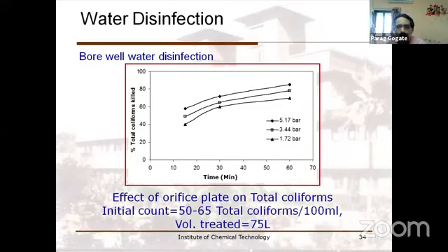So again, in earlier days, we also tried using hydrodynamic cavitation for water disinfection. Like you talk about borewell, there might be some microorganisms present. So why can't we use hydrodynamic cavitation? Because in a borewell, you have a flow where your water is coming from the Earth's crust into the surrounding atmosphere, and there definitely flow is there. So I can introduce a cavitating device in the borewell, and then I can use it for disinfection.